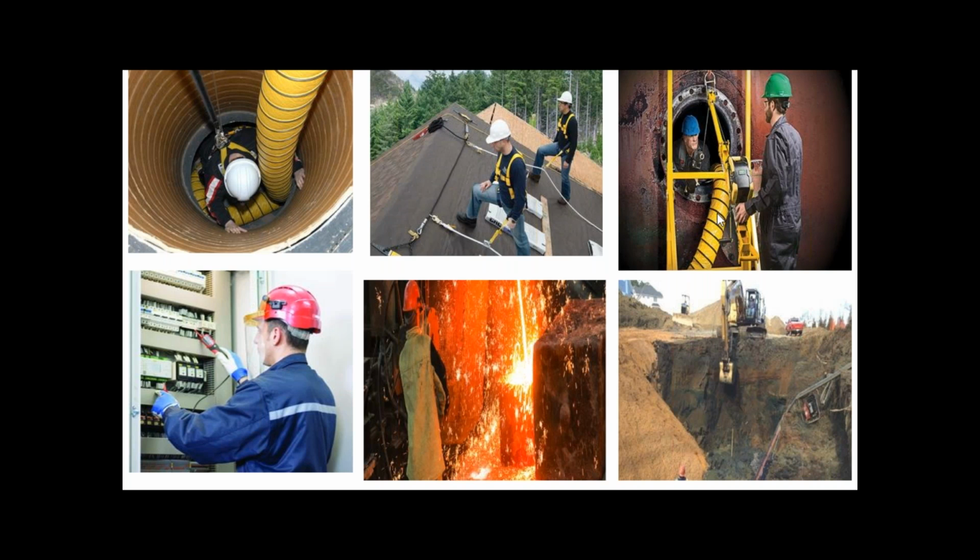So for that purpose, you have to check first whether all these liquids or gases or vapors are present in that tanks or not. So for that purpose, you have to check these gases or vapors with the help of digital meters, so that we can understand whether all these vapors or gases are within the permissible limits or not, or is there any other issue in that tank. And if all these things are okay, then we can supply or support with some facilities that we have shown.